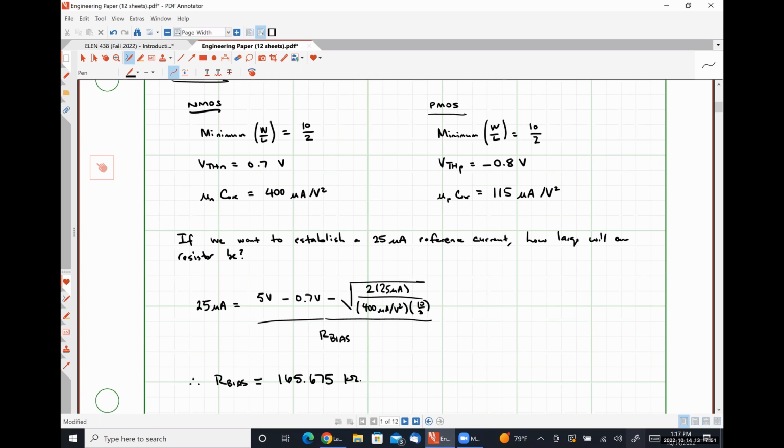There were like 12 people in a city on a cell phone. So that's another very important thing. The channel selectivity did not have to be nearly as precise. So your filters didn't have to have nearly as high Q values because you're not having tens of thousands of users operating on the same extraordinarily narrow frequency band. Also a lot more noisy, and they're probably transmitting with a whole lot more power. Yeah, the batteries were definitely a lot beefier.